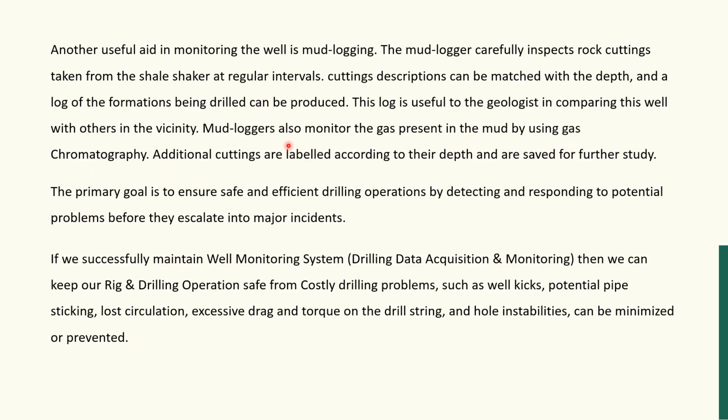The mud logger also monitors whether gas is coming in the return mud from the formation to the surface. If the mud is mixed with gas, then the driller will activate the degasser. The degasser is a solids control equipment through which the gas is removed and the clean mud is pumped to the mud tank. The primary goal is to ensure safe and efficient drilling operations.